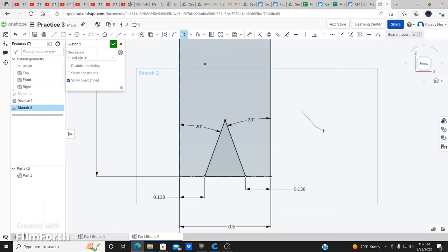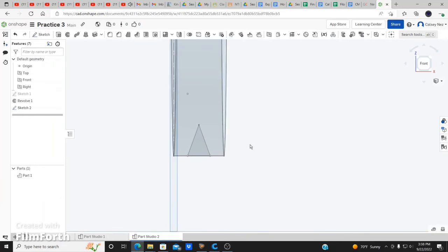Most of the other software has another function, which is this one right here, trim. I'm going to hold down and select this area, hold down my left button, and just trace along the way. And then you guys see it actually deletes those right away. So you don't have to worry about clicking them one by one. You can drag and just trace along the lines that you want to delete as excess material. Okay, let me deactivate it. Check it. Now we've got this right here.